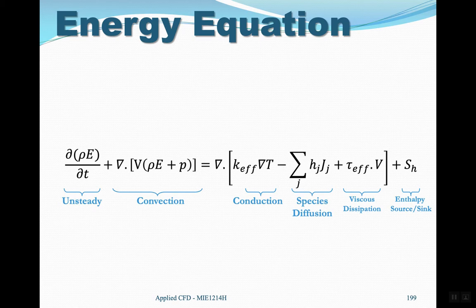As you know, inside a pipe the flow at the wall has 0 velocity, and it increases as you go further from the wall. These different layers of fluid with different velocities create friction between each other, and the friction causes heat dissipation, which is called viscous dissipation.